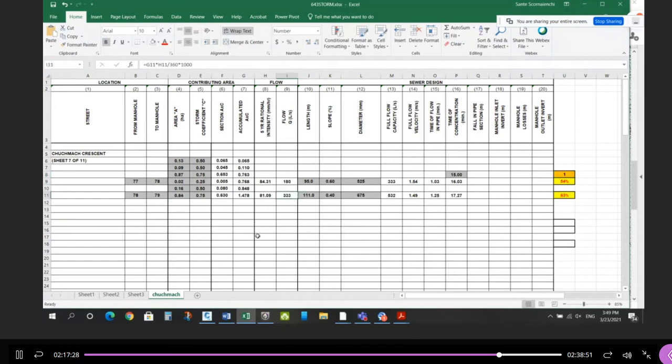That increases this flow, expected, but not the capacity. And now this percent full goes up. So when I make this 0, before our subdivision took water the wrong way or the other way, this was the pipe capacity, 46 and 53%. Add the additional area to those two pipes. It goes up to 54 and 63, which means these two sewers have capacity to allow the north strip of our site to go through.